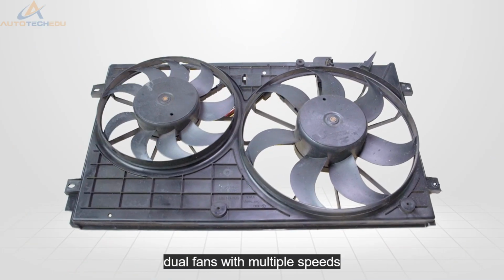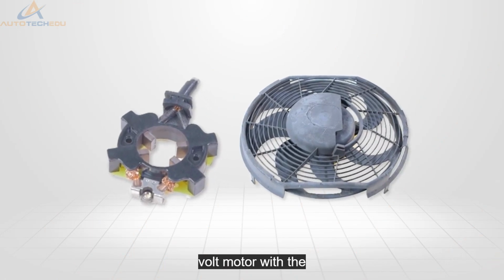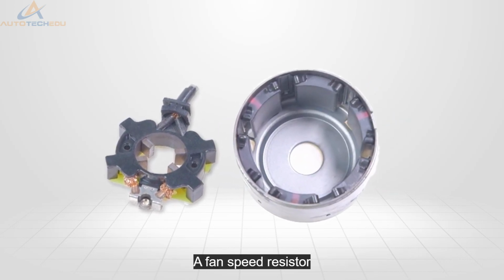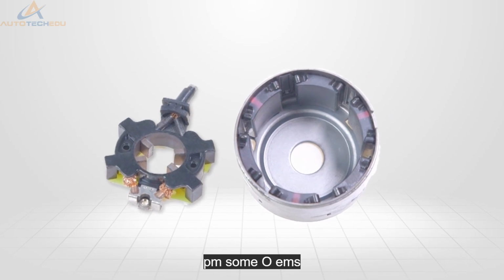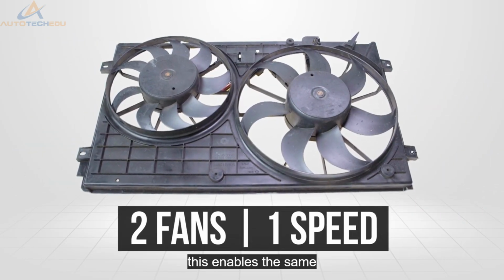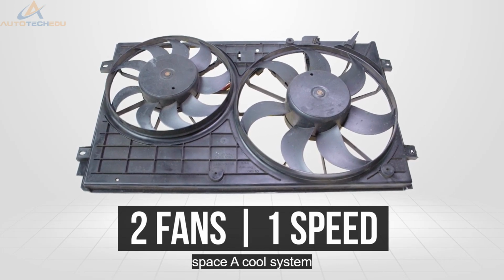with multiple speeds. A single fan will normally comprise of a 12-volt motor with the internals consisting of either 2 or 4 brushes and the corresponding number of permanent magnets. A fan speed resistor may also be used to alter the fan's RPM. Some OEMs may use 2 fan motors operating at 1 speed. This enables the same airflow as a single larger fan but takes up minimal space.